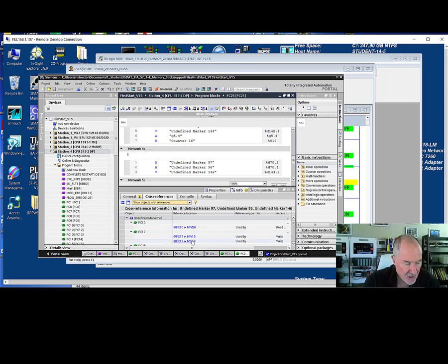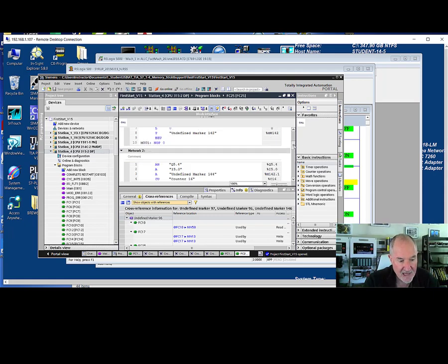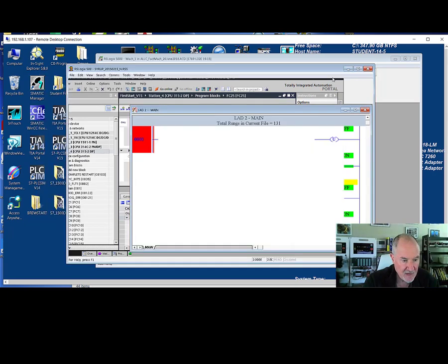You have this cross-reference down here, and of course, as I mentioned before, you can look at the assignment list, see what was used in the assignments. You can look for symbols and things like that, usually cross-reference from the symbol itself, and hopefully, if what you understand is ladder and your program's written in ladder, you'll be able to trace things down. So that's a little bit of an example there of Siemens.